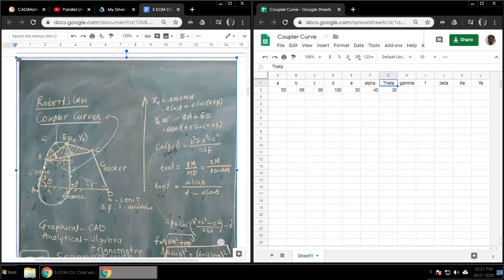Here the value of e is known, of course it's a constant, the length between points B and E. We have two angles here. Alpha is the angle on the linkage, so it's not going to change, whereas beta, the small angle which you see here, is the angle of the line joining BC with the horizontal. That angle of course is going to change.